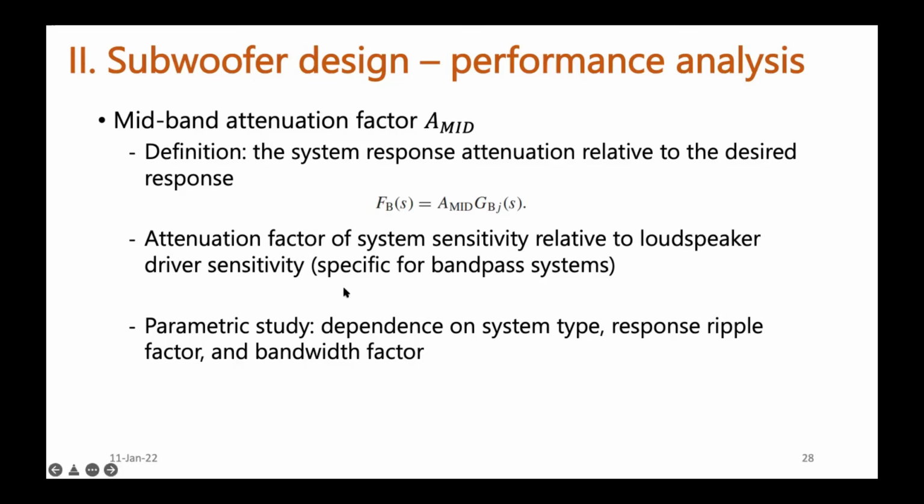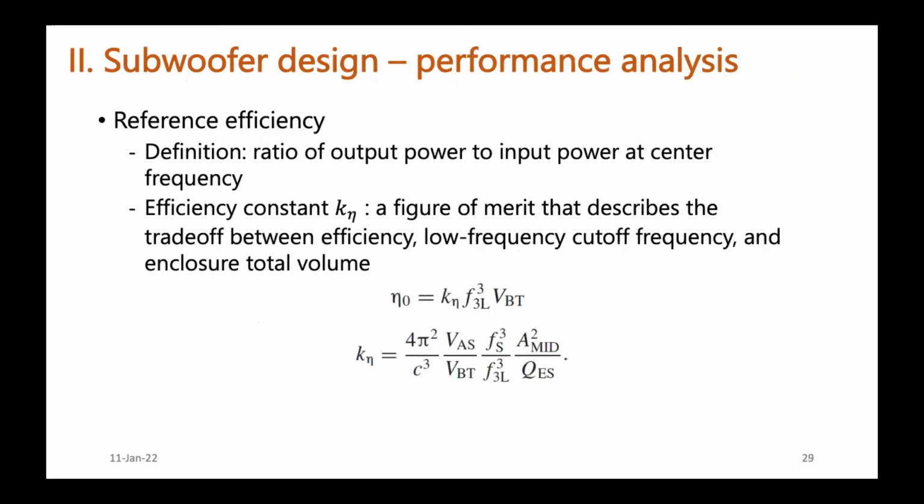The driver sensitivity is the case for the driver mounted in an infinite baffle. Then we can do some parametric study to learn the dependence on the system type, the response ripple factor and the bandwidth factor.